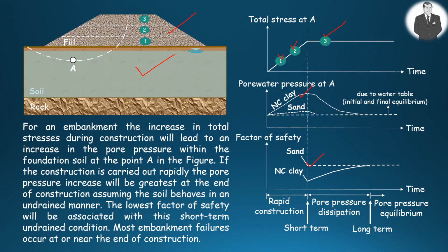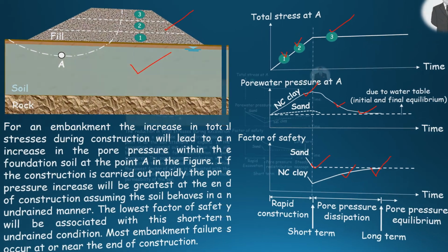But with time, as the pore pressure dissipates, as you see in the figure, the factor of safety will increase accordingly. Therefore, most embankment failures take place at or near the end of construction.